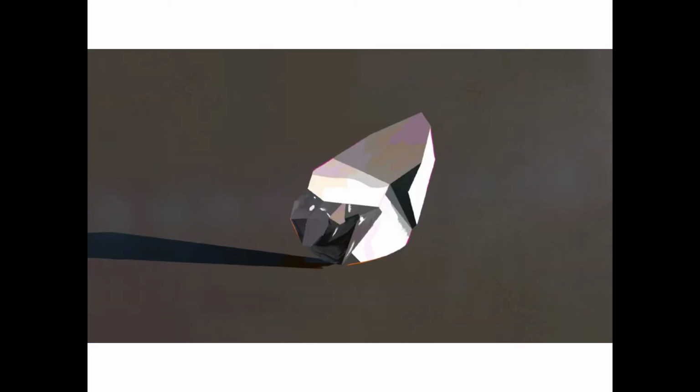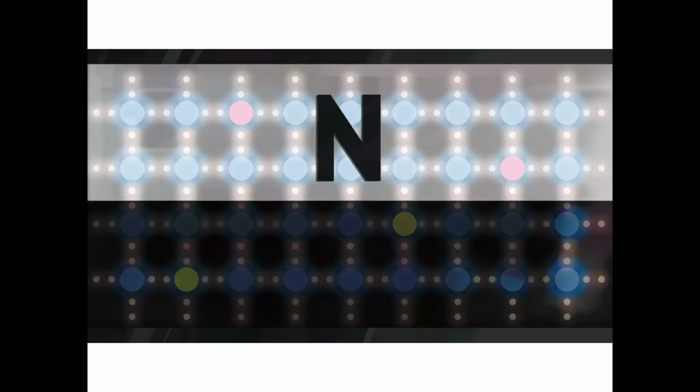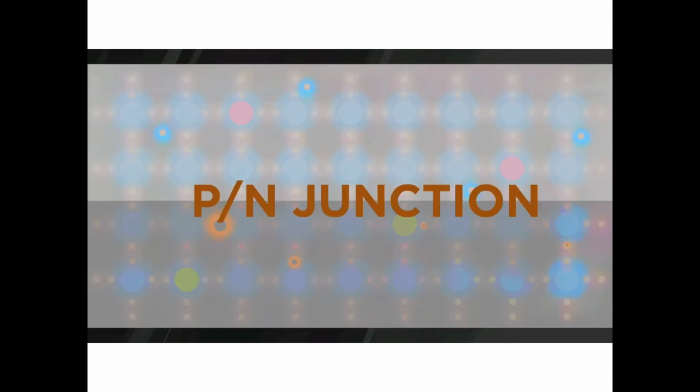In a solar cell, crystalline silicon is sandwiched between conductive layers. Each silicon atom is connected to its neighbors by 4 strong bonds, which keep the electrons in place so no current can flow. Here's the key. A silicon solar cell uses 2 different layers of silicon. N-type silicon has extra electrons, and P-type silicon has extra spaces for electrons, called holes. Where the 2 types of silicon meet, electrons can wander across the p-n junction, leaving a positive charge on one side and creating negative charge on the other.